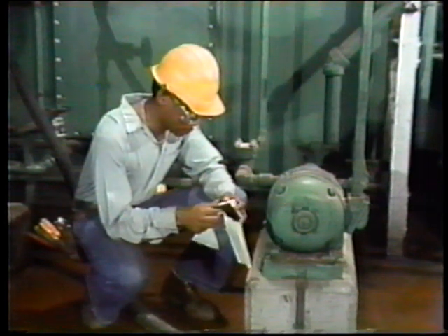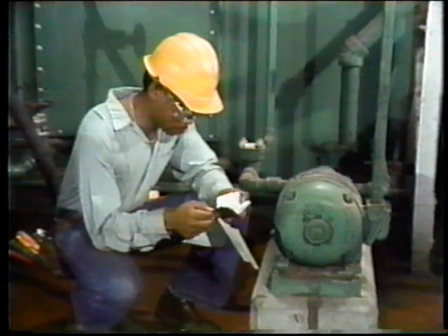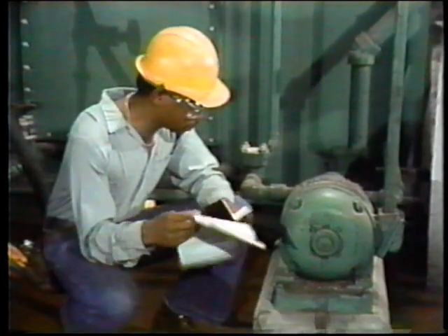Well, it's a 2.68 amp, 440 volt, 3-phase AC motor. One look around the area tells him there's going to be moisture in the environment, and he'll have to allow for that. But as far as temperature is concerned, it won't exceed 86 degrees Fahrenheit or 30 degrees centigrade, so that won't present any difficulties.